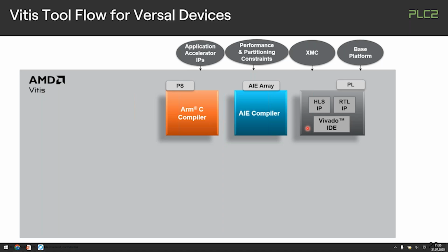So we need a software definition to create our subsystem, and that's exactly the next step. So the tool chain allows you to combine these different elements into a runnable design, which means we have a linking step that picks up the CPU ELF code, that picks up the AI engine content as configuration data for this array and the ELFs for the singular vector processors.